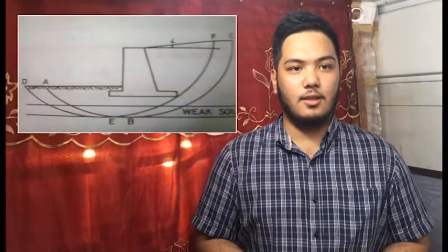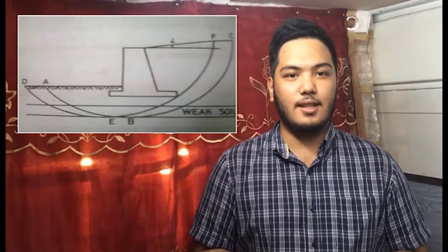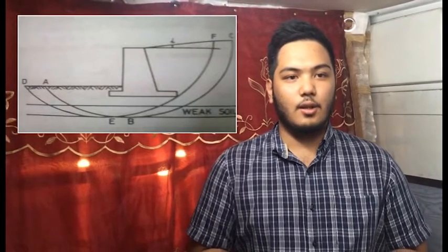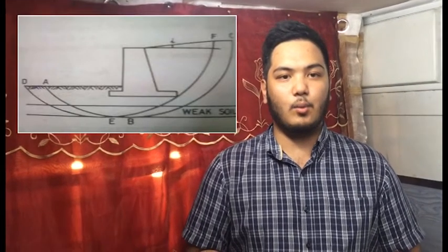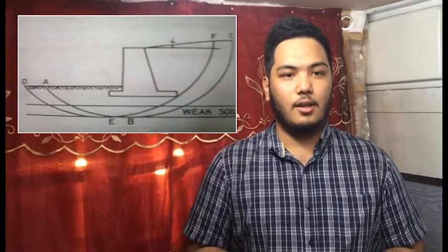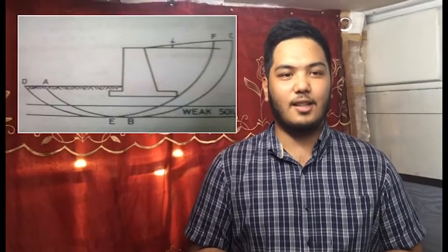Lastly, fifth, deep shear failure. This type of slope failure occurs along a cylindrical surface ABC, as shown in the figure. When there is a weak layer of soil under the wall at a depth of about 1.5 times the height of the wall, the critical failure surface is found by trial and error method.